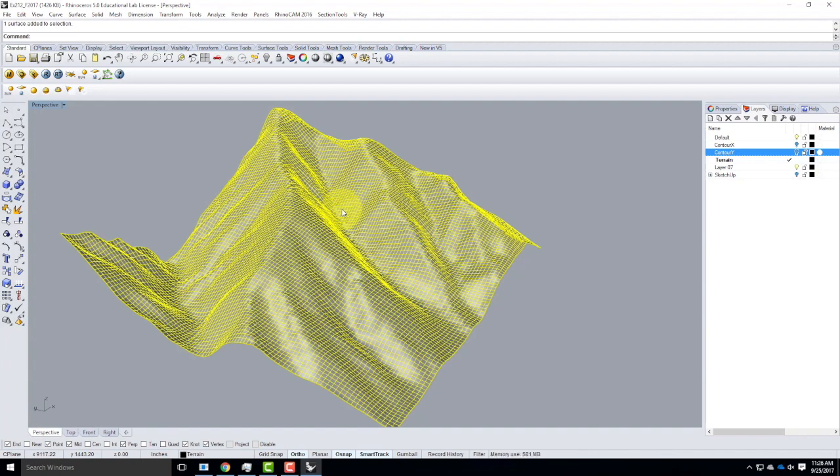So the bed of the laser cutter, and a lot of you guys have already laser cut, so this is old news for you, is 12 by 24. So that's the maximum size sheet that we can fit. So 11 by 17 fits rather nicely in that 12 by 24. It's unlikely that you can actually cut a full 12 by 24 without doing some manual cutting. So don't ever think that, oh, I could just make a 12 by 24 and glue them together or something. You need to have something a little bit smaller. I'd leave at least 1/4 of an inch around the outside of that 12 by 24. So you're really more at 11.5 by 23.5 as the maximum size that you can cut on the laser cutter.